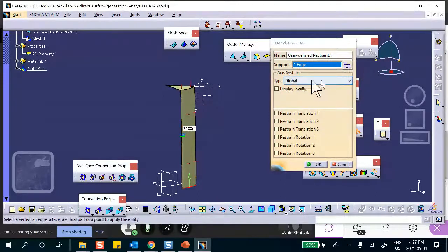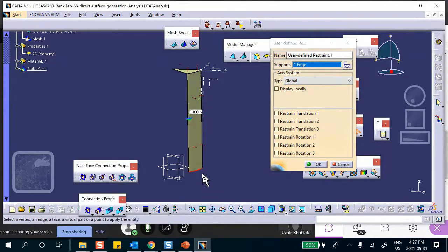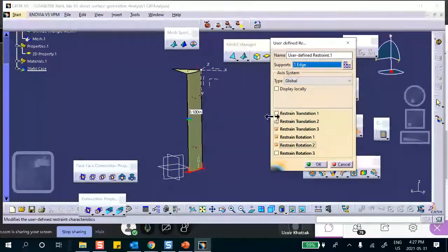One of them is the global one. See, it's global right there. But there's also the local one. As far as this goes, it is in the global XY. Global XY means it does not move in Z. Translation in Z is fixed. And rotations are opposite. Don't forget the rotations. You have to do it. No part marks.